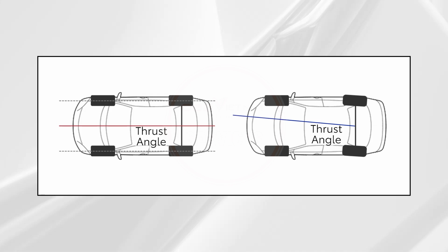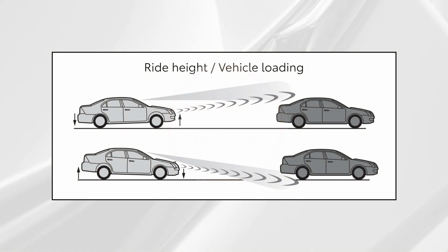When a vehicle dog tracks, the center line of the body is not pointed in the true direction of travel. The repair procedures for many of the front recognition camera diagnostic trouble codes start with making sure that both ride height and alignment are correct.